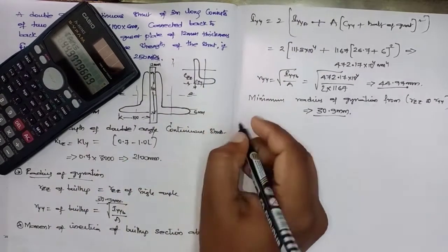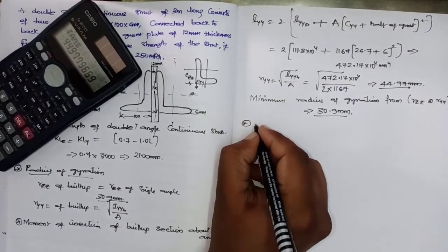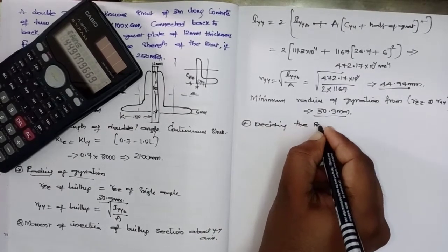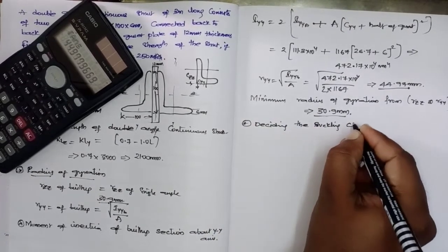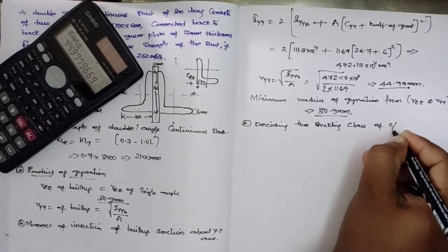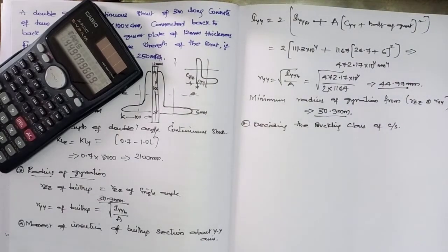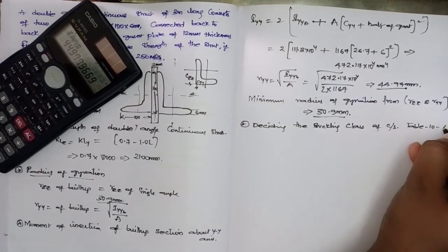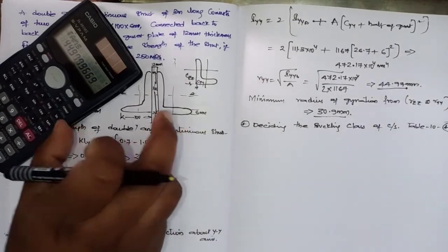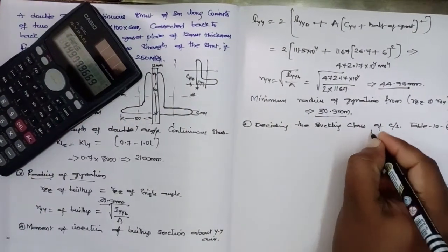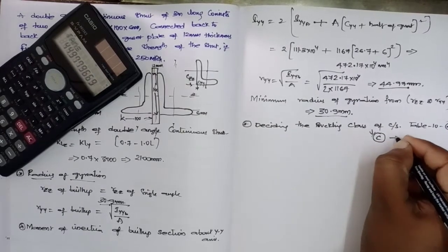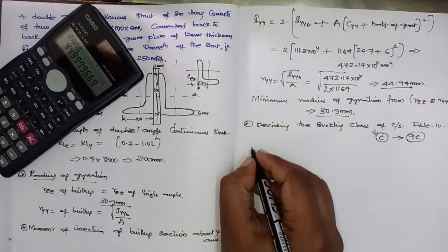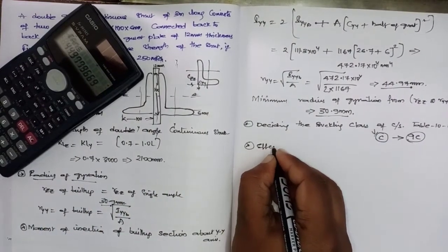Now earlier we have discussed deciding the buckling class of the cross section. As per Table 10 of IS 800:2007, page number 44, any angle section or built up section comes under buckling class C. Means you have to visit Table 9C. Now the effective slenderness ratio.